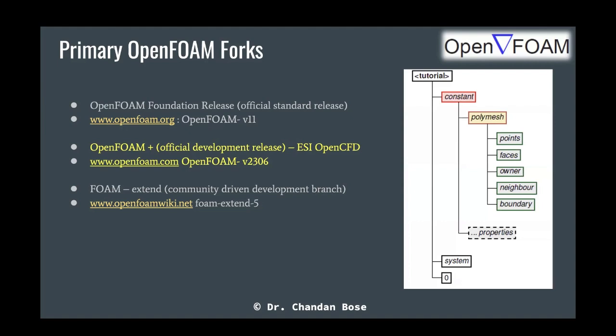So this is very important: when you go to any tutorial to get started with OpenFOAM, you will have a case folder, right? You will have a tutorial folder. Whenever you click the folder, you will see a bunch of files. And then the new starters get confused about what these files are, which file to change, and what they mean. So this is the basic structure of any OpenFOAM tutorial, and it does not change.